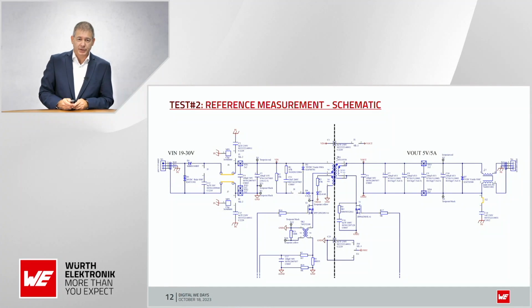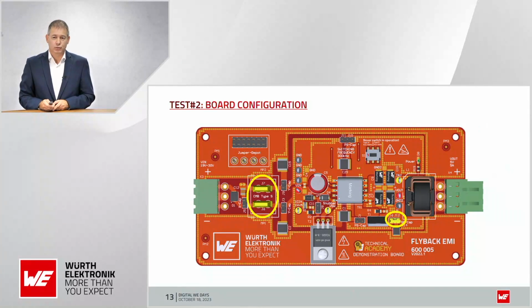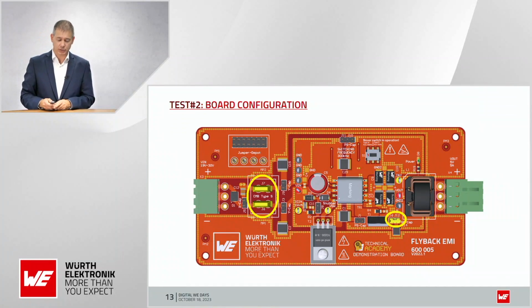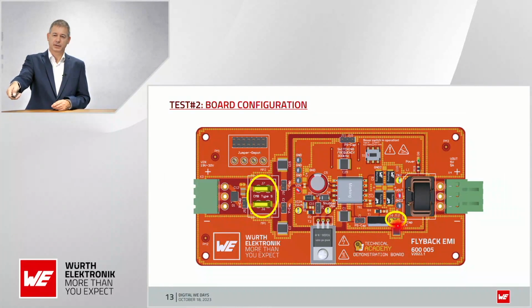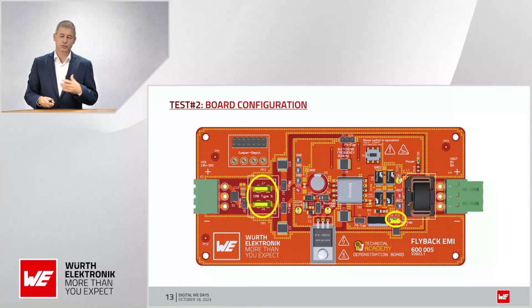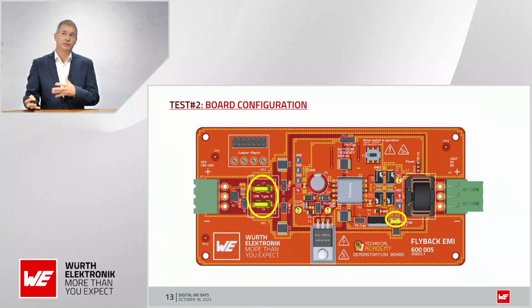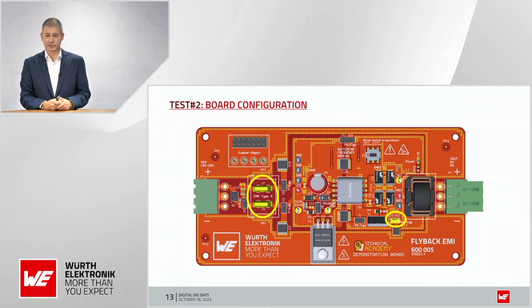The next point is the configuration for the first frequency domain measurement. We add here a shortcut. We remove the common mode choke we will use later on, and this jumper activates this capacitor. It's a capacitor down to the base, to the functional earth. Then we get a feedback or a return path to the ground for common mode currents.